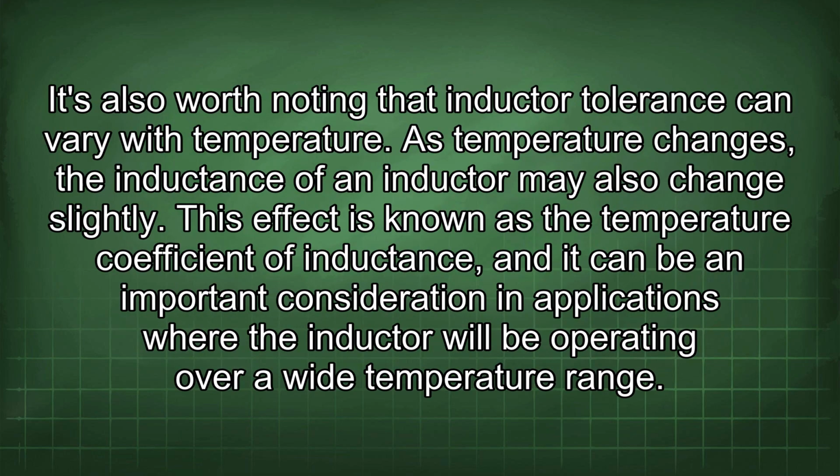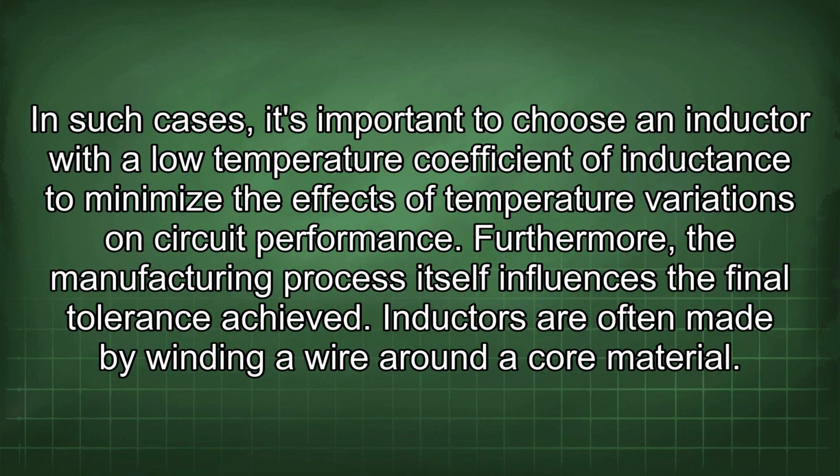It's also worth noting that inductor tolerance can vary with temperature. As temperature changes, the inductance of an inductor may also change slightly. This effect is known as the temperature coefficient of inductance, and it can be an important consideration in applications where the inductor will be operating over a wide temperature range. In such cases, it's important to choose an inductor with a low temperature coefficient of inductance to minimize the effects of temperature variations on circuit performance.